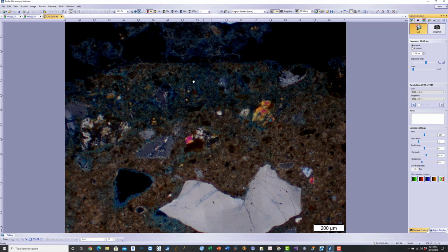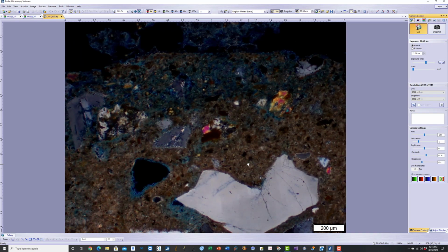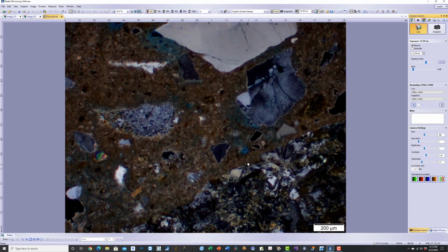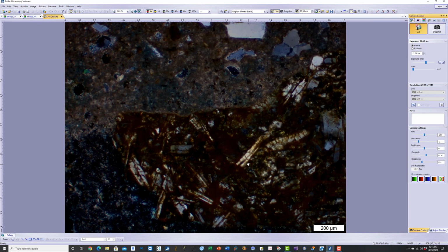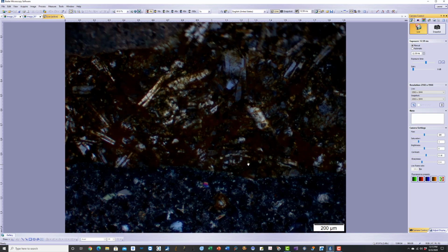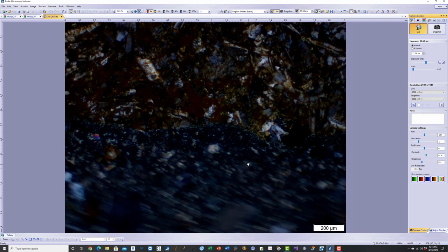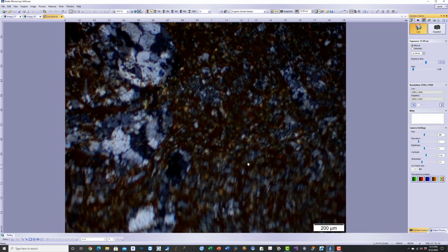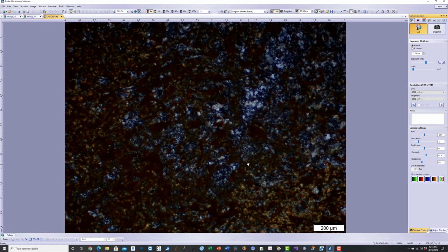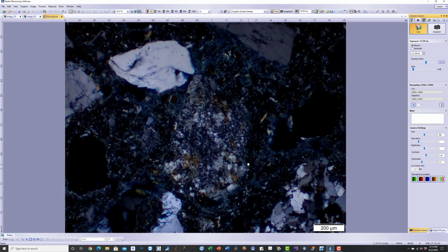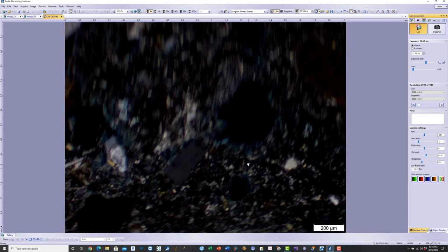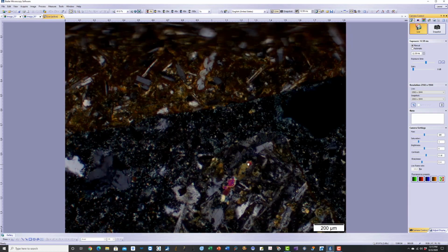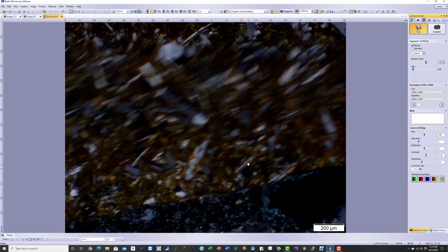This is the concrete part, the mortar on the top, and then the dense portion of the concrete is carbonated. Then after this dense surface region comes the interior. You see a volcanic rock here, dacite and andesite. Now comes the interior, a rhyolite. Now this is the interior non-carbonated portion of the concrete. And you can see a lot of volcanic rocks.